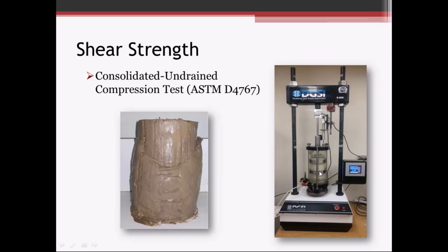And this test also determines the undrained shear strength for short-term loading. But one of the things that can be done with this test is we can measure the pore pressures that are developed during the test. And with that information, we can determine the drained shear strength parameters, which can be used to evaluate the long-term conditions.